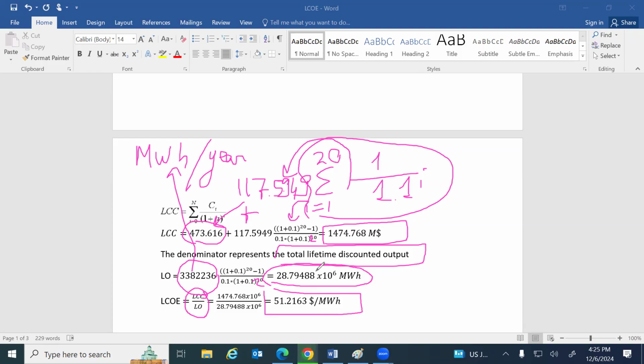Capacity value percentage, is there a difference between the type of fuel used or the type of solar? Yes, of course. The capacity factor mainly depends first on the type of renewable. If it's a renewable energy project, it will be much lower. In general, nuclear power plants and plants relying on fossil fuels will have very high capacity factors because of the availability. You have fossil fuel, whenever you need it, you can use whatever quantities you want. While for renewable energy, it depends a lot on the climate and on the season.